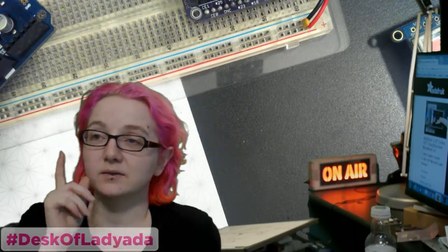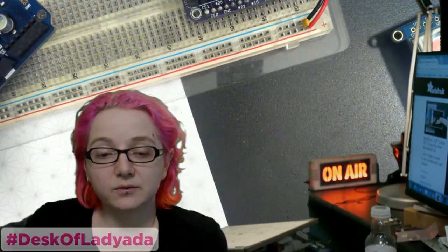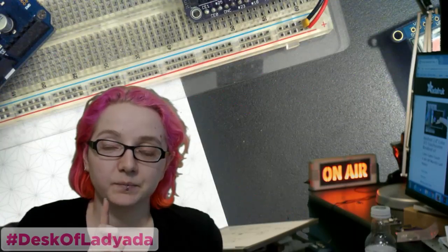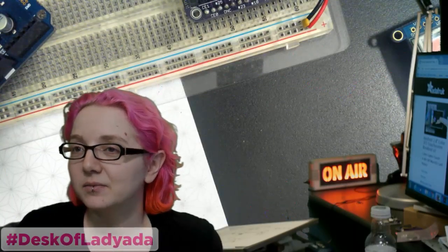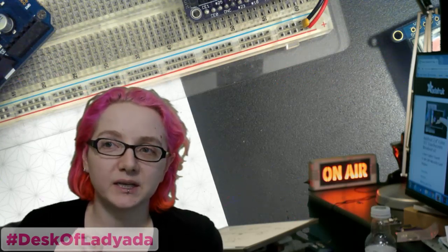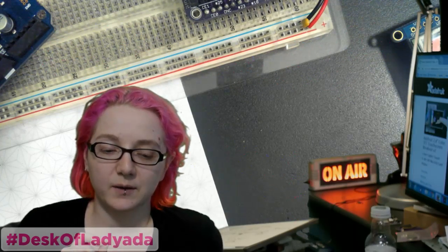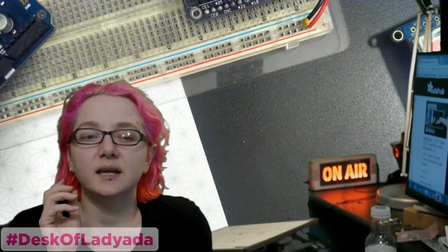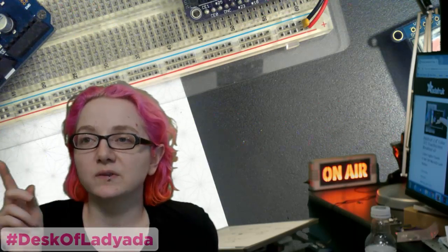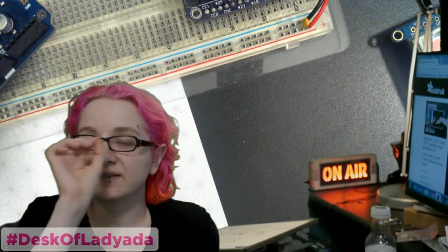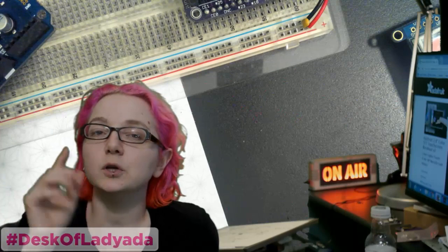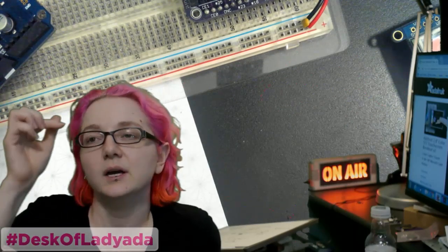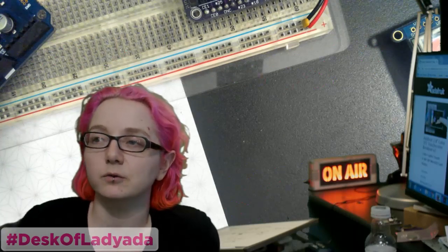Something I've actually done, by the way, just reminded me because I was thinking of a gyro that I really liked from Maxim. I ended up not using it, but the chip was under NDA, but the eval board was not. The eval board came with evaluation software. So you pay a little more, like $60. I got the eval board, and then I sniffed the I2C connection, and the eval board let you set all the settings, so you could extract the register map very easily by changing one bit at a time and seeing what register it changed.